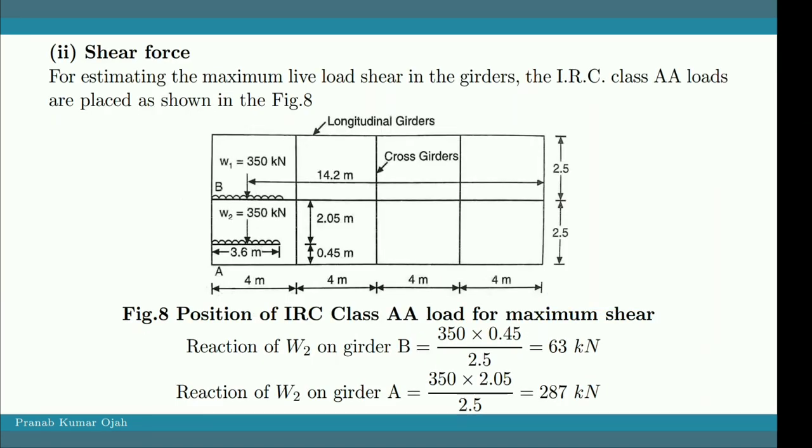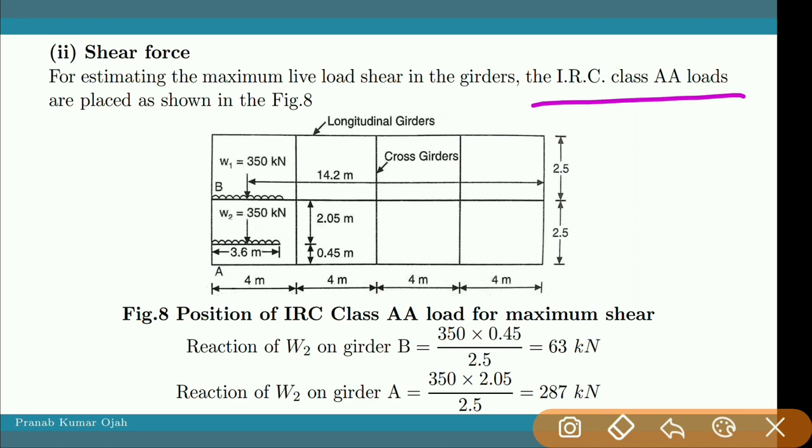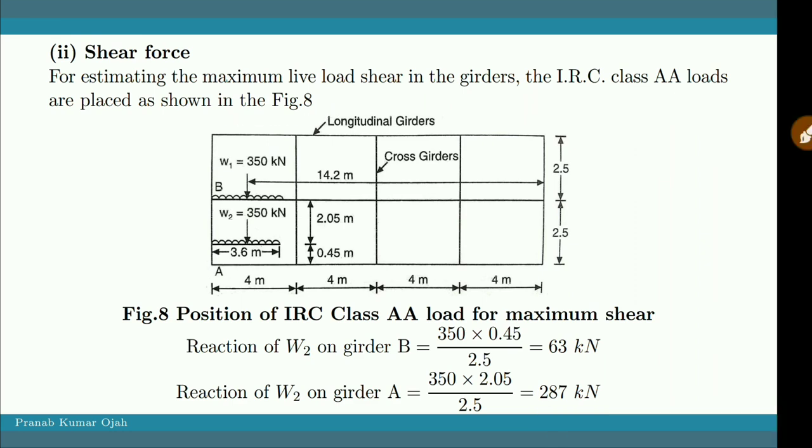Now we have to calculate the shear force for the live load. To calculate the shear force for the live load, you have to place the class AA loading as shown in figure 8. As all of us know, the shear force becomes maximum when the load is nearer to the support.